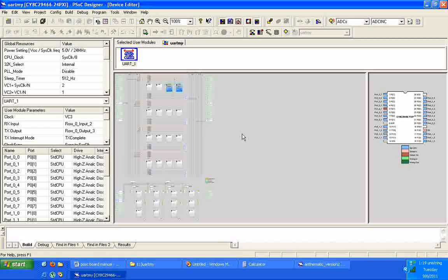In our PSoC microcontroller, port 2.7 is internally connected with the transmitter, and port 1.6 is internally connected with the receiver. We simply need to place the jumpers at the UART2 port. Then these two port pins are internally connected with the transmitter and receiver.